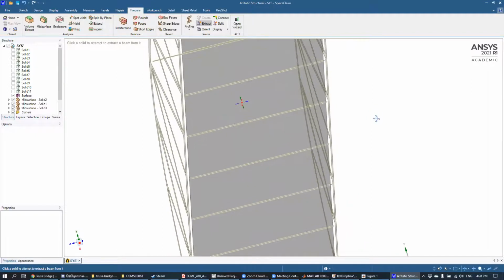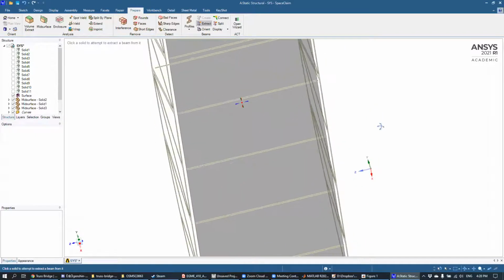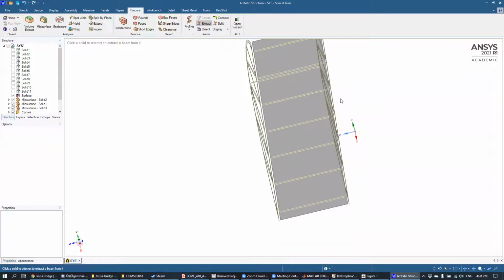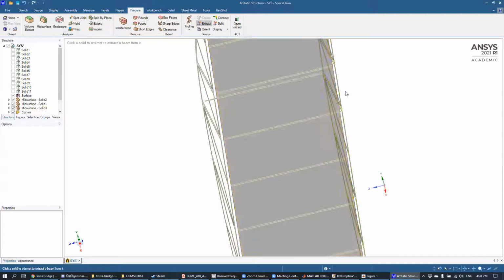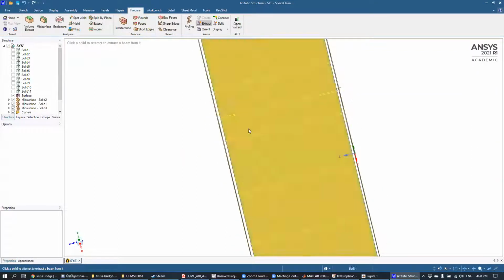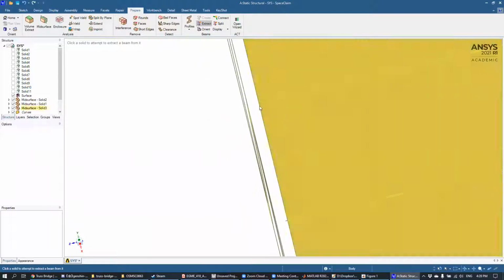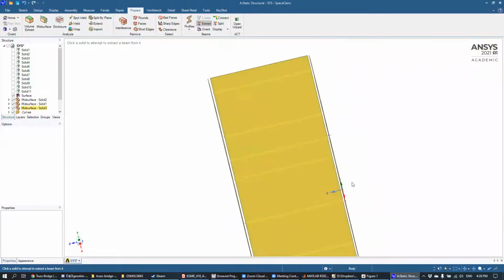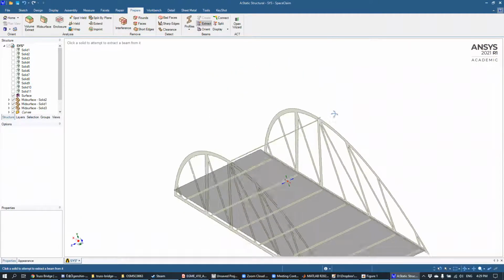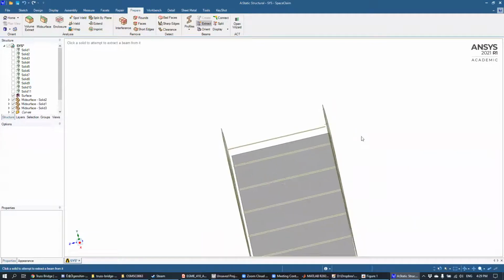And that's one of the main dangers when you convert things, that you lose thickness information. The main place where you lose that is when we converted the side supports here. You can see this beam is no longer touching that one, and that's a problem. We need to make sure that these connect. That's going to be the subject of the next part of the activity.